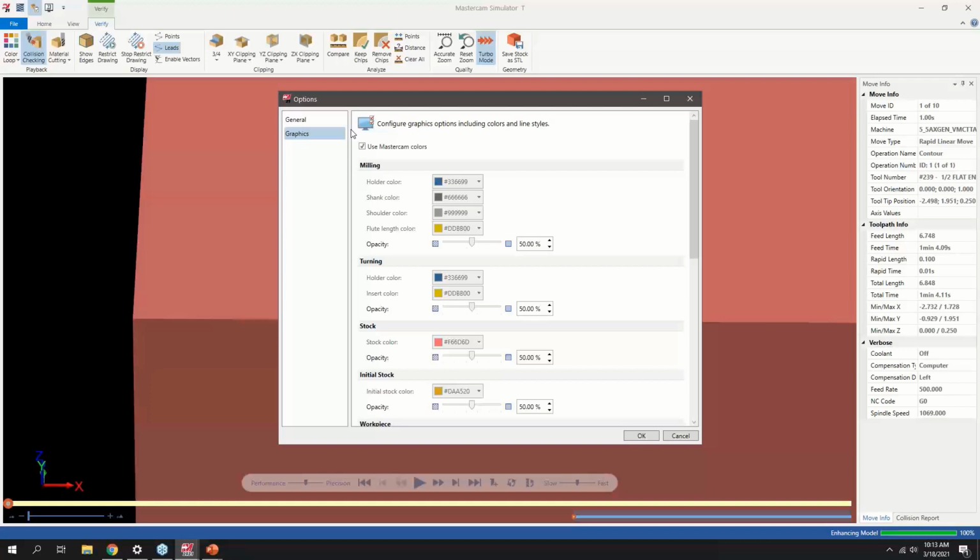And the big difference between the two is the 3-axis engine is going to take liberties when it comes to displaying your part. So a circle won't be a circle, it'll be a very jagged edge. So if you've ever verified a flat end mill going straight across the line and it looked very jagged on that wall, that was the 3-axis engine simplifying it for you and making it fast and dirty. The 5-axis engine will be faster, but it's going to take an extra step after the fact to smooth everything out to be more realistic.